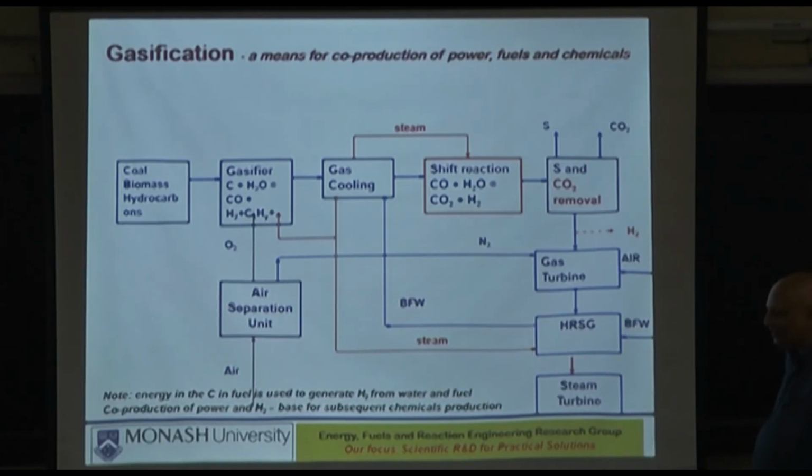But at the end of the day, in the gasifier you have to produce certain amount of CO2 because that supplies the heat. That reaction, carbon plus oxygen giving you carbon dioxide, supplies just enough heat to give you the carbon monoxide, to sustain the endothermic reactions, which I will show later on.